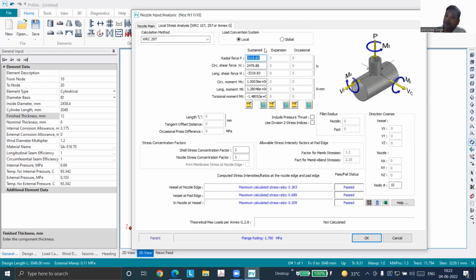So if you feel that the radial expansion is going to be governing, okay, but before the project is finalized, that is also difficult to predict. The only basis you can say is that if the temperature is very high, you can imagine that because of this temperature your thermal or linear expansion may be more. Considering that, you can evaluate. But finally, the length of that pipe is going to be the governing criteria for this force.